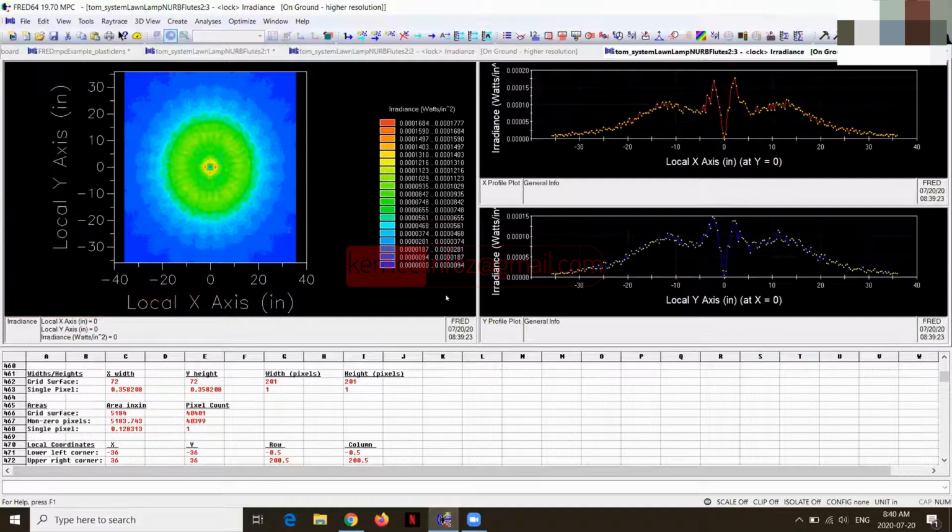Yeah, FREDmpc doesn't do any sequential ray tracing because it's usually unnecessary to trace billions of rays in sequential. So it's just never been written for FREDmpc. In both cases, Monte Carlo and ray splitting, it is non-sequential. It just means that in Monte Carlo the number of rays does not increase during the ray trace, so it's easier to handle or predict calculation times and statistics. That's the reason. But there are times when you want to use one over the other, and that's the same for all ray tracing, and for the CPU as well.